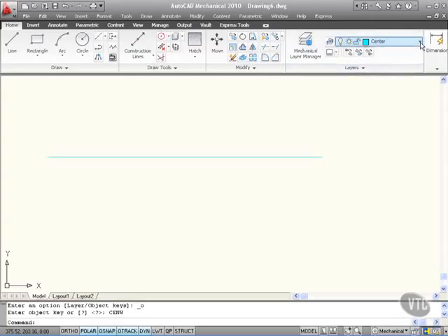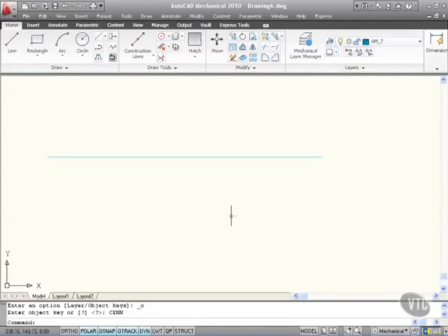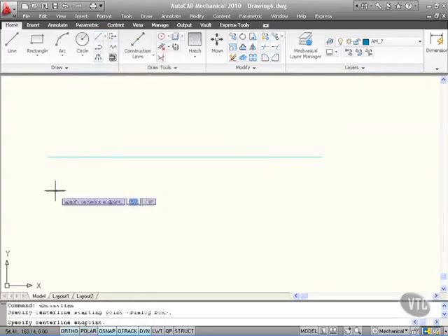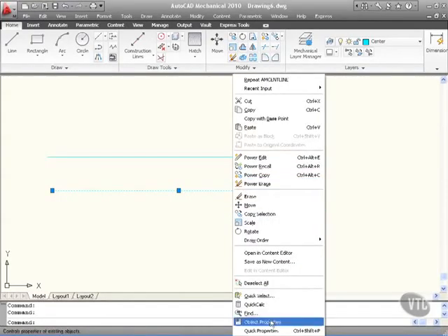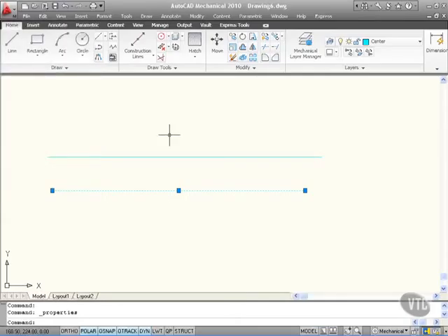So what I've got to do there is I've actually got to go to AM7 here, and then if I click here, let's try another center line and see what happens. There's the AM7, but look, if I go and draw a center line again, it defaults back to my center layer. You can see the color is the same. If I go back to object properties, you can see it's still using that center layer, like so. So let's close the properties palette there, and let's hit escape.